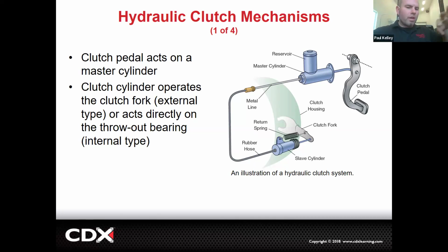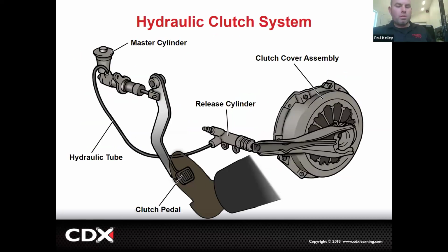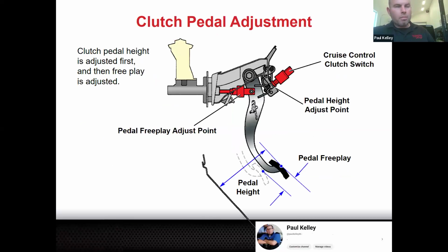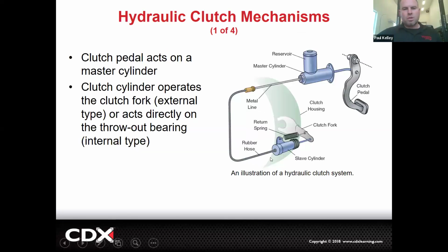Okay, makes sense. All the other stuff is a drag, and a slip is just going to be caused by that long push rod adjustment. Insufficient clutch pedal travel or clutch play, right? Like right here we were talking about, the pedal free play would be insufficient. That's a slip. Everything else is a drag.